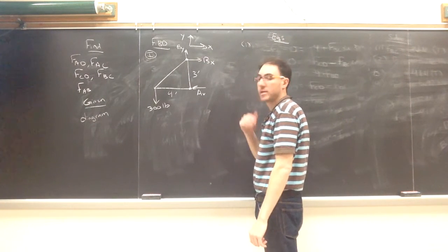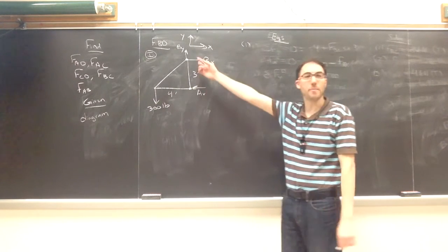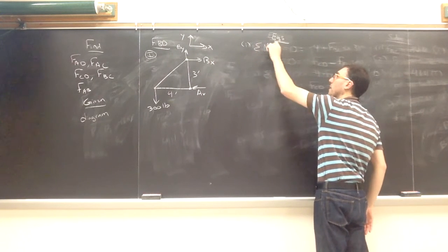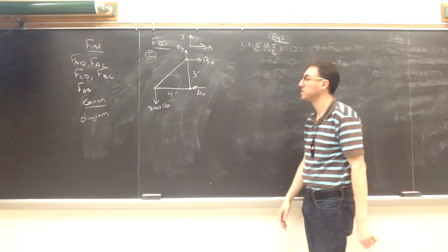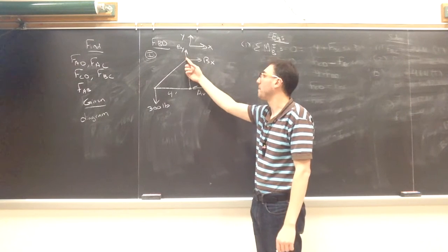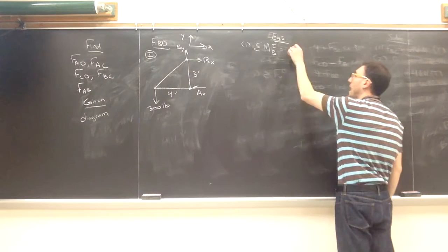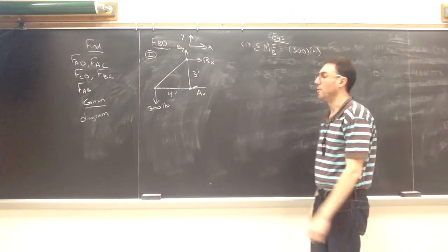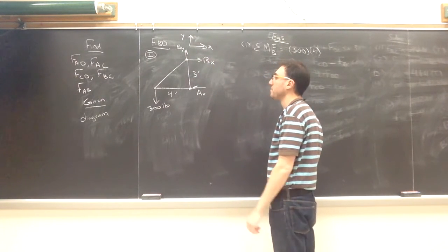So we can start with the sum of forces or the sum of moments. In this case, because we have a pin at B, actually it's going to be easiest to start with the sum of moments around that point because we'll be able to immediately get one of our unknowns, namely AX. Taking the moment around B, BX, BY will not be in that equation. I will have a moment caused by the 300 pounds that's 4 feet away. That will be positive or counterclockwise around point B.